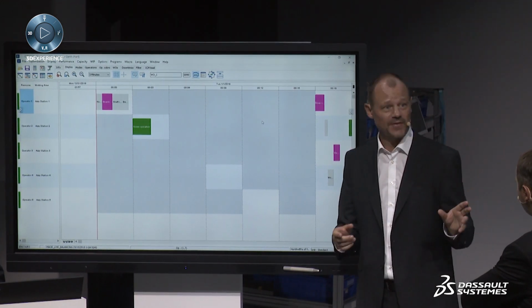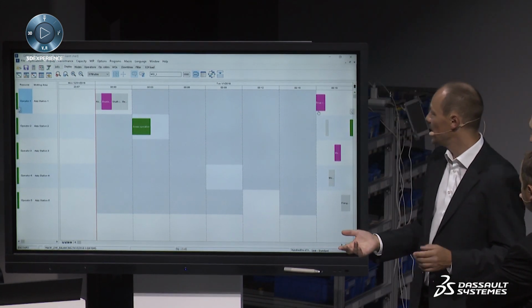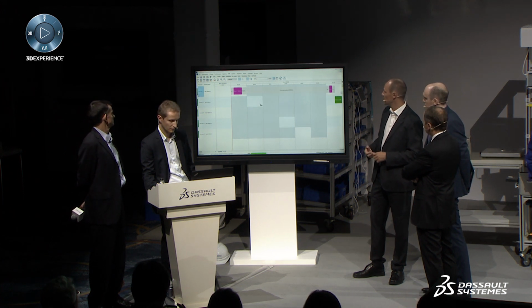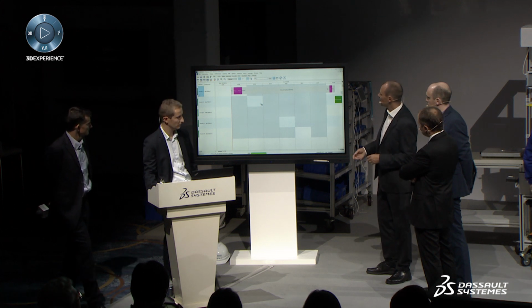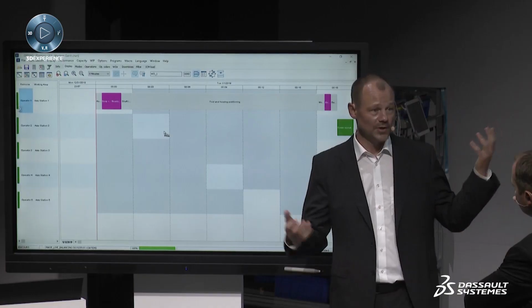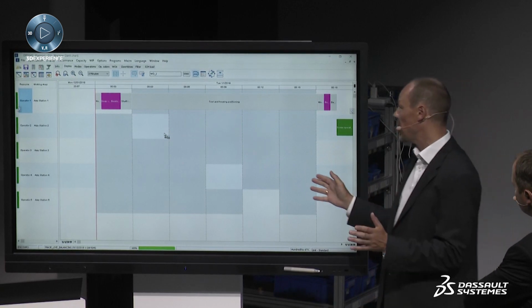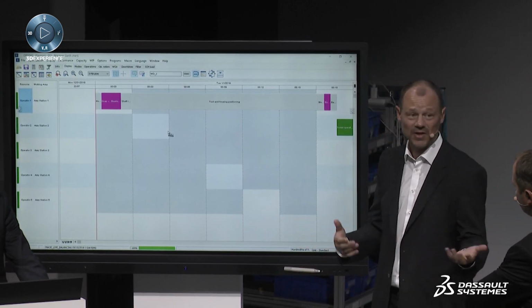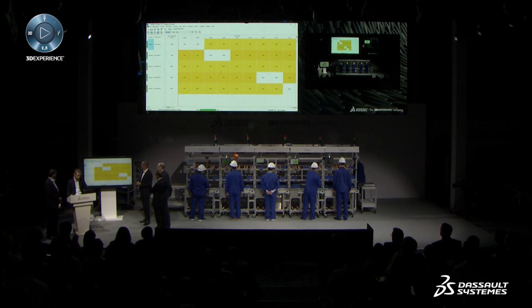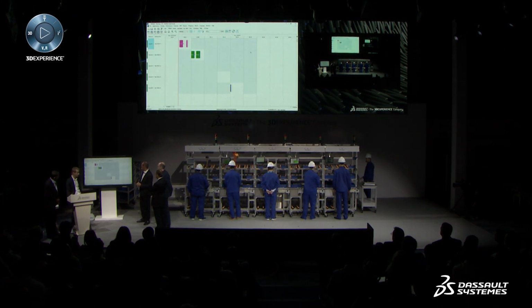What we can try is, because we have a second routing, what we saw before in our work plan, let's try if the second routing is working here. We change our simulation, our test, to the second routing, and we simulate this, and it looks a bit better because we have much more operations connected now to stations 1 and 2 that are already available. But we see it is not working in our takt time. Maybe it helps when we just double the takt time from 3 to 6 minutes. Let's check what this idea brings us, and yeah, almost good. It's good.